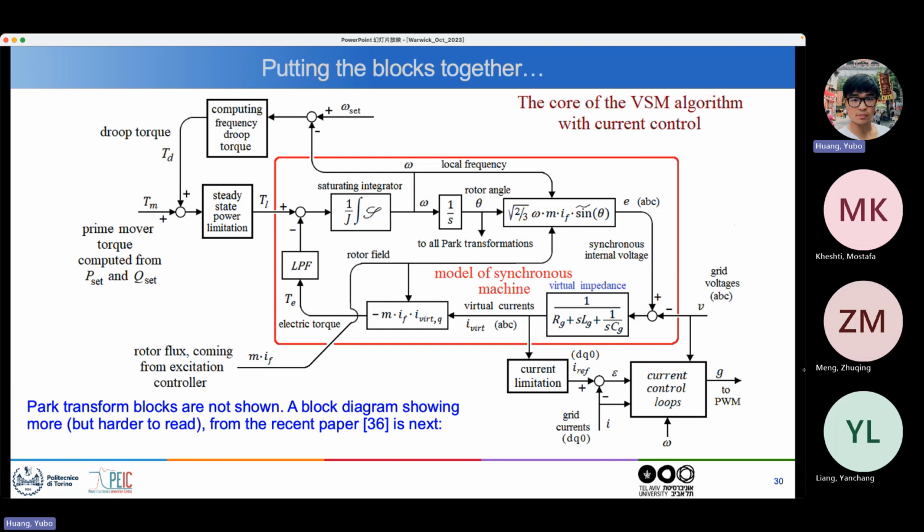Why do you need a series capacitor in the stator impedance? Of course, in a real stator, you don't have a series capacitor. This is to prevent DC currents. This capacitor will stop any DC current that might, by mistake, flow through your stator winding.